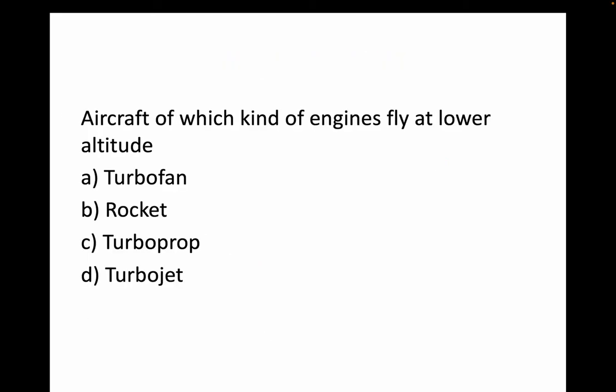Okay. Now, which kind of engine powers aircraft that fly at lower altitude? Rocket is simply ruled out of the question because the rocket goes into space, so that's not an option here. Then if we see turbofan and turbojet, we find most of the commercial aircraft operating at almost 36,000 feet, which is pretty high altitude. So the only option that remains is turboprop.